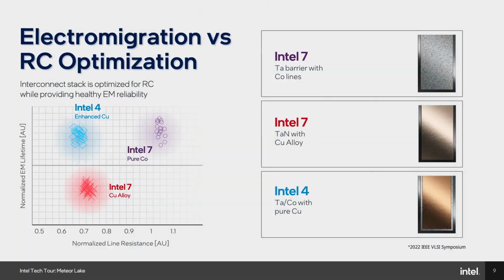We developed what we called enhanced copper. By implementing this new type of wire connection, you have also reduced the RC or the impedance on it. Resistivity on those lower metal layers. If you compare resistivity or the conductivity improvements that we have in metal 0, metal 1 compared to Intel 7, it's a significant improvement.